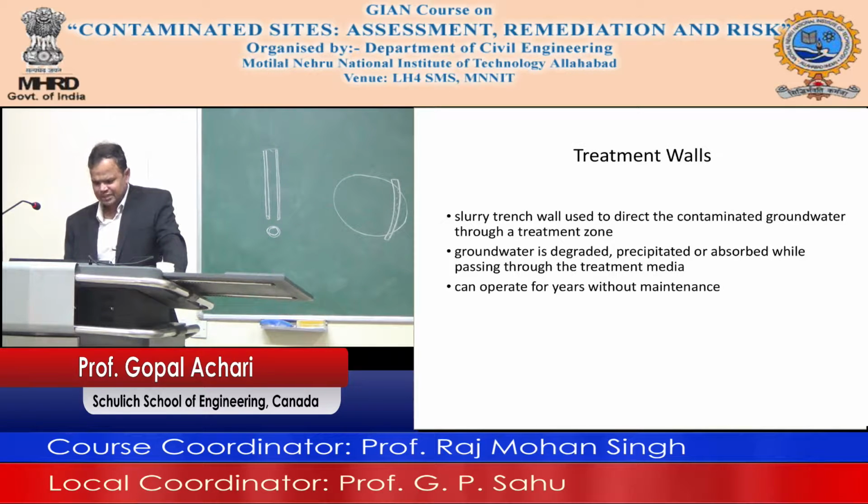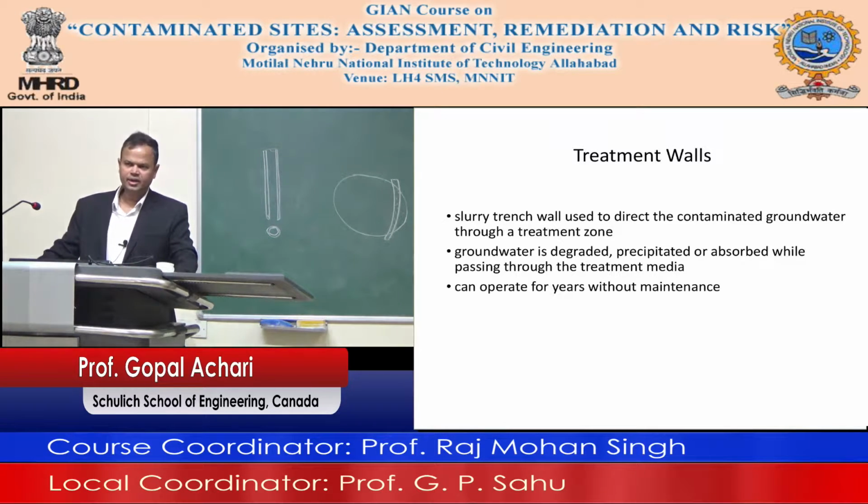So this is a cap. What I talked to you about earlier was a liner. Cap means the top. You have a vegetative layer here, for the top soil. Below that, you have a protection layer for the top soil because you don't want things to migrate up. You have a granular layer, which provides drainage, as you can see here. Below that is the geomembrane, and then the waste. There is also a gas collection layer. Basically you want to make sure that there is no water buildup.